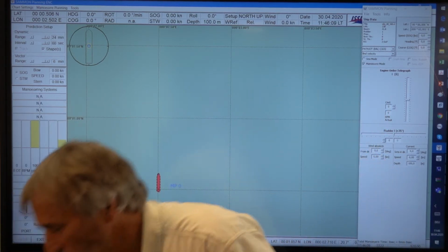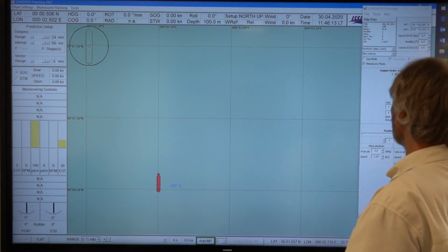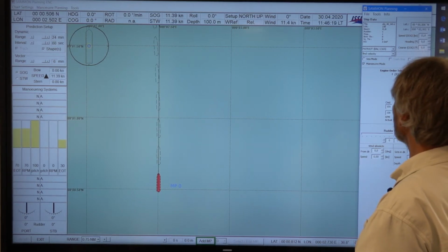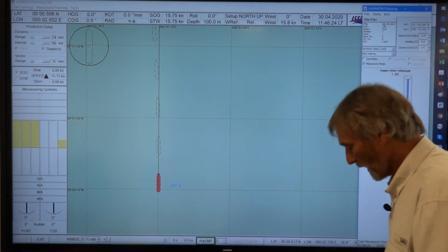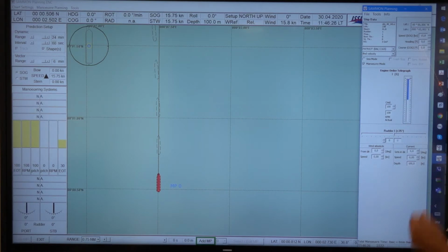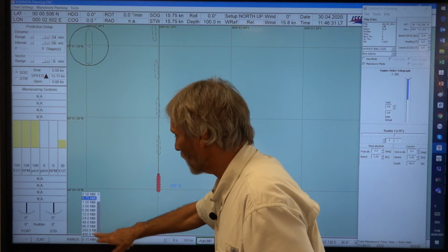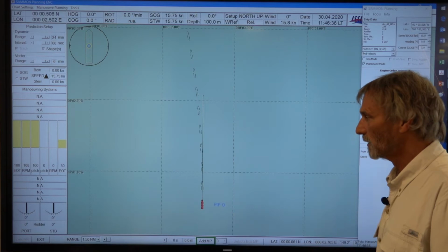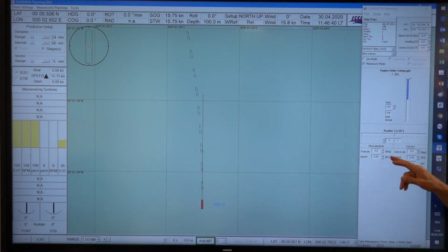This means we have the ship here, it is a tanker. And I push the tanker now to, let's say, full ahead. It's a speed of about 15.8 knots. And you see the tanker is not really going straight because it's a single screw vessel. And due to the propeller effect, you need a certain rudder angle to stabilize this.